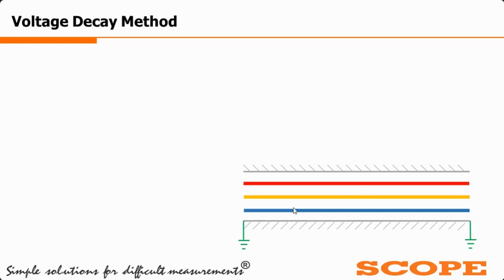In certain conditions, mainly in India, cable fault location manufacturers build surge generators of up to 32 kV levels only. Let us consider that a very small insulation failure has occurred in the cable. It is called a pinhole type of puncture or insulation puncture. This type of cable has very low leakage current through it.